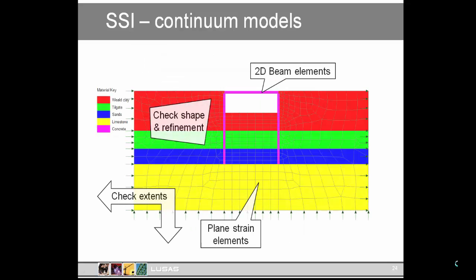So we've got our model with Mohr-Coulomb material or other nonlinear material model. But wait, we've forgotten something. Mohr-Coulomb material was designed for regular soil. It wasn't designed to take soil ratcheting into account.